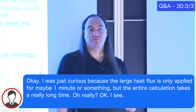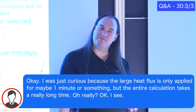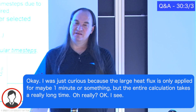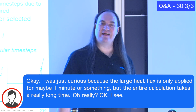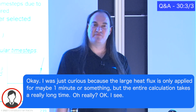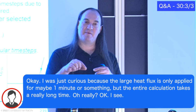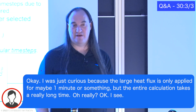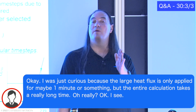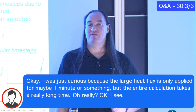So it's another variable. I think it's actually per submodel, but that doesn't make any sense to me because it doesn't solve one submodel at a different time step cadence than a different submodel. So why it's not a single global variable, I don't understand, but I think that it is submodel specific. So if you needed to set it, you'd have to loop through all the submodels and set the D time I for that submodel to the new value. But I believe that would be a better way to do it if you know in advance when your event is happening and you want to slow it down for that so that you don't miss it.